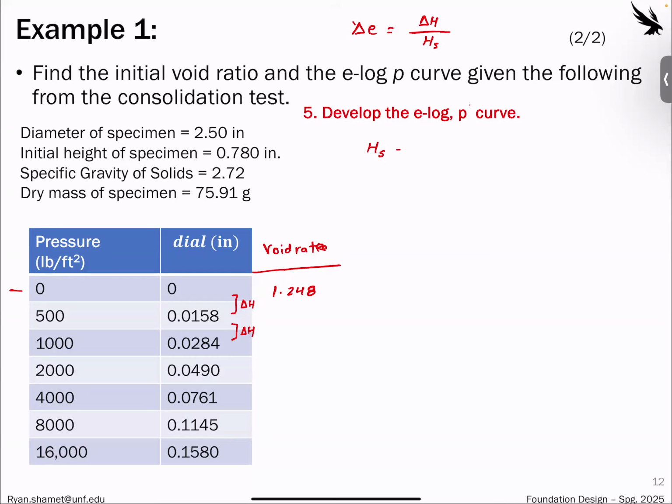So in order to find the height of the solid, this is our Vs divided by the area of our puck. Volume of the solid is height times area, so we can find it conversely that way. If we do that, calculating it using the area, then our height of our solid is 0.881 centimeters. So that's our pseudo height of our solid in our sample.